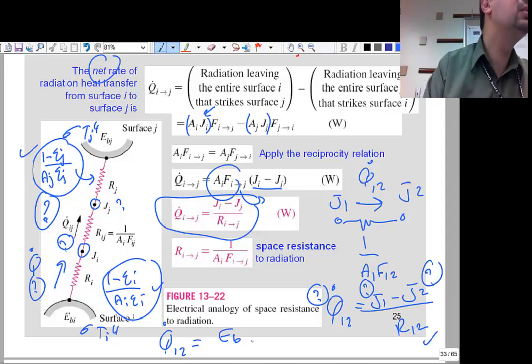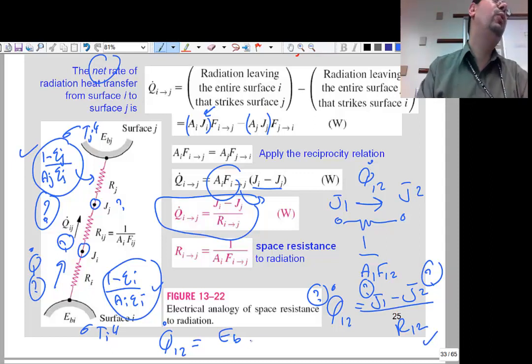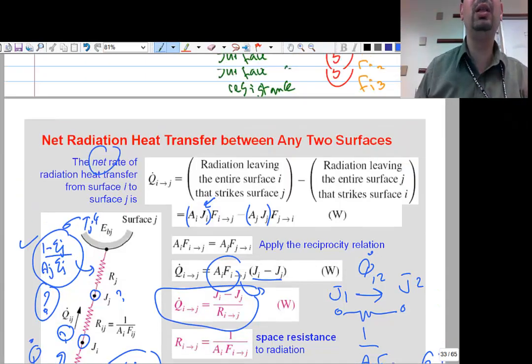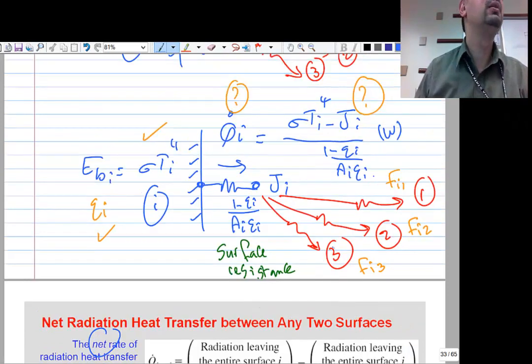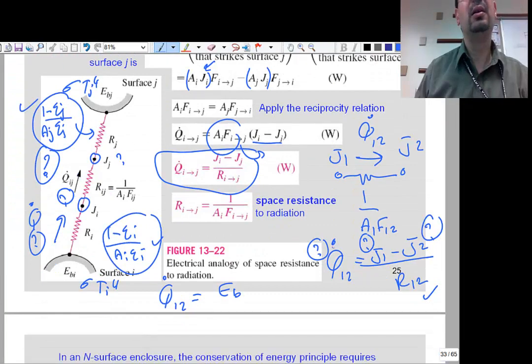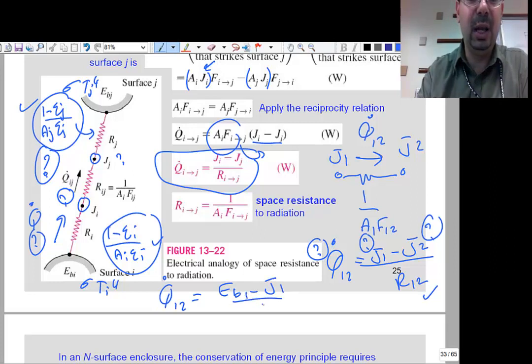We wrote that before, and we know the problem. We don't know the Q, we don't know the J, right? That's what we said here. Set the Q's equal to the whole thing, so you can set those two equations equal to each other. That J minus the equation you have over on the right, you set it equal to the EB minus. So you are saying make it like this and put the R surface 1 here and let it equal to this. And then how can I get my Q? I still don't see it. No, because I have J1 and J2.